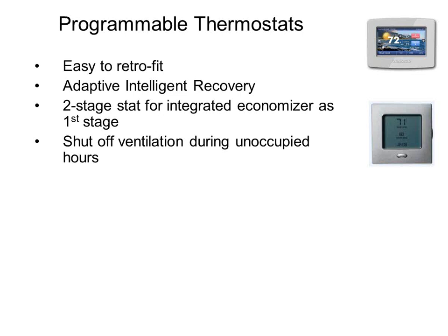The building automation guys have done a pretty decent job of this over the years, but if you don't have a building automation system, and you just have a regular thermostat, every single night, every single time there's a heating and cooling call, you're opening up the ventilation damper and bringing fresh air in for people that don't exist. It's the biggest waste of money you can do on a rooftop, and it's so easy to fix.